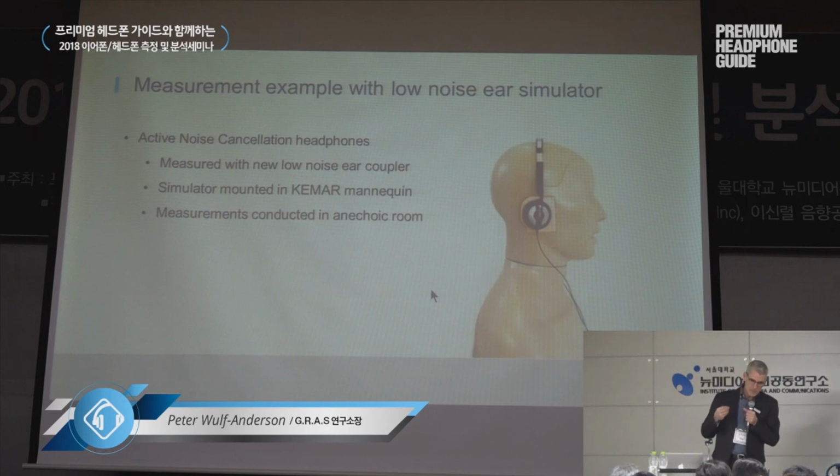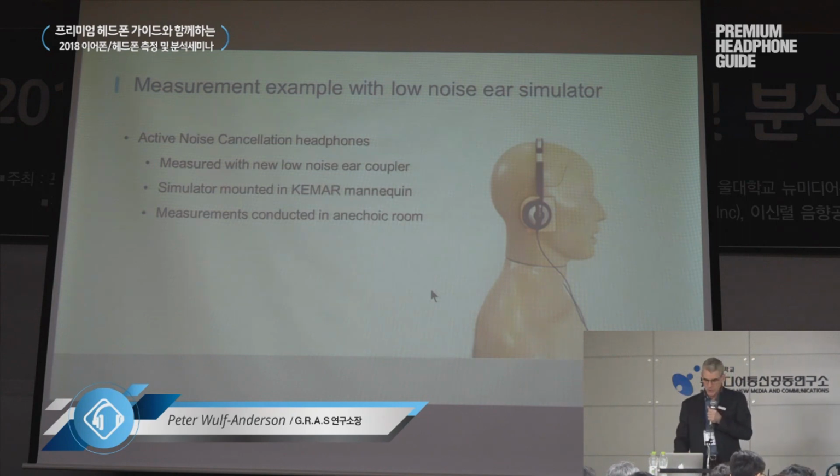To give you a simple test and show you what happens, what we did was we took our mannequin, the head and torso simulator, put it in an anechoic room, and we did a background noise measurement, and we did a measurement with the headphones in passive mode, meaning no noise cancelling circuit turned on, and there was no music, meaning no signal to the headphone, just trying to find out what the background noise is.